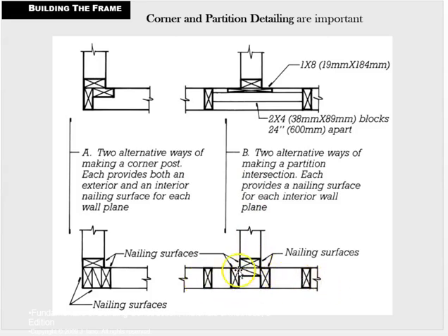Coming over to this one now, we have the interior partition meeting the exterior. So in this version, we have full height studs, and then we have some blocking, and then we have a stud here to provide our interior corners. Insulating in here, again, difficult. So that would be a void, because it could be done from the outside before the sheathing goes on, but here we have 3 studs creating a void, so not preferable. Probably very sturdy and rigid.